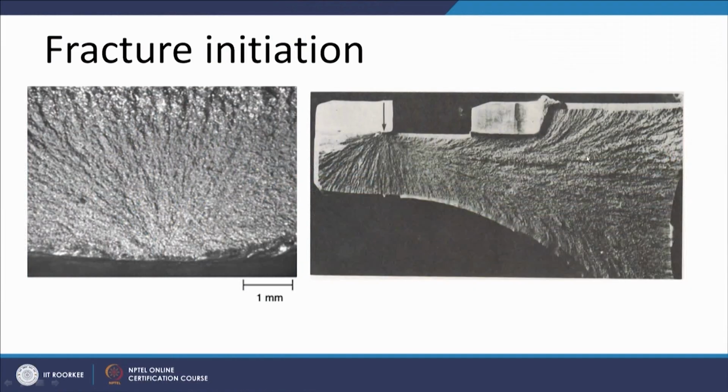Similarly here, if you see, this is the fracture surface and all these are pointing towards this direction, and here all these are also indicating one direction. So, this is the location which indicates where the fracture has initiated.